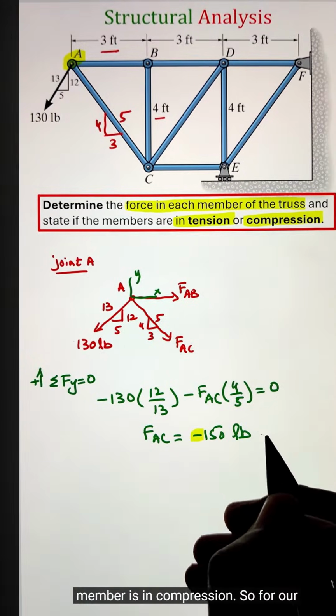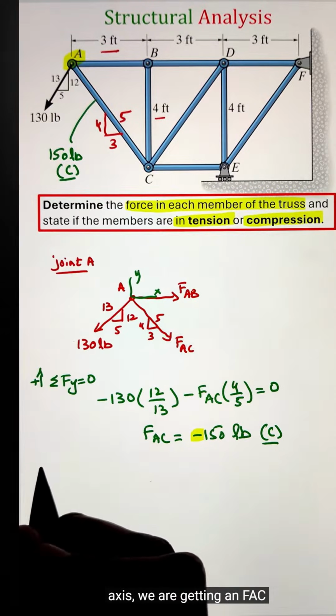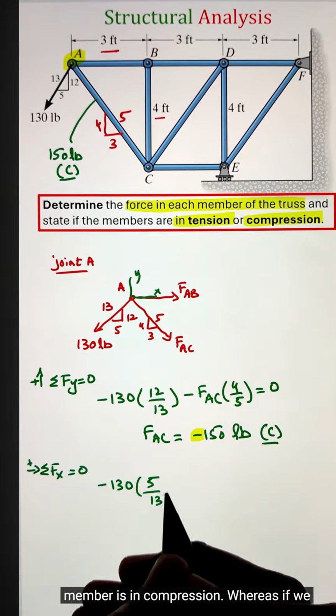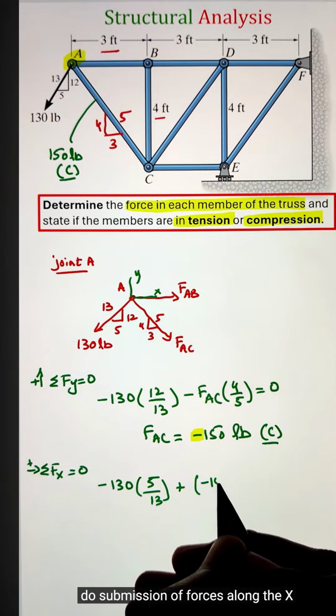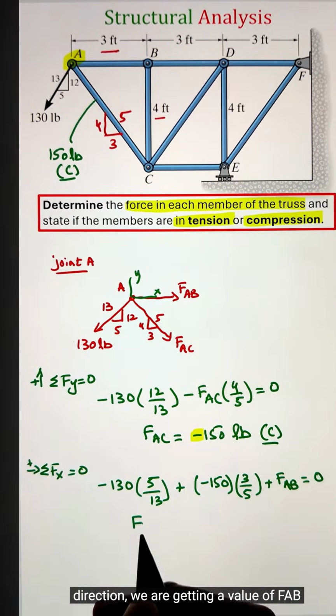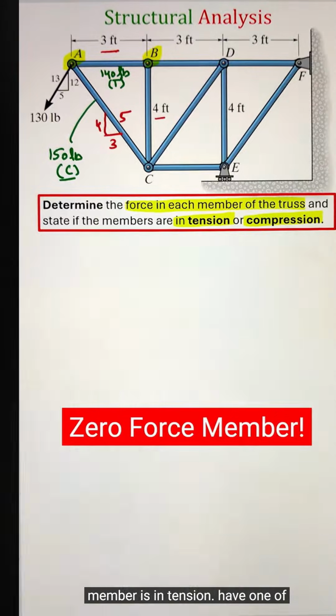For our summation of forces along the vertical axis, we are getting an FAC value of negative 150 pounds. That means the member is in compression. Whereas if we do the summation of forces along the x direction, we are getting a value of FAB equal to 140 pounds. This means the member is in tension. Now next, move to joint B.